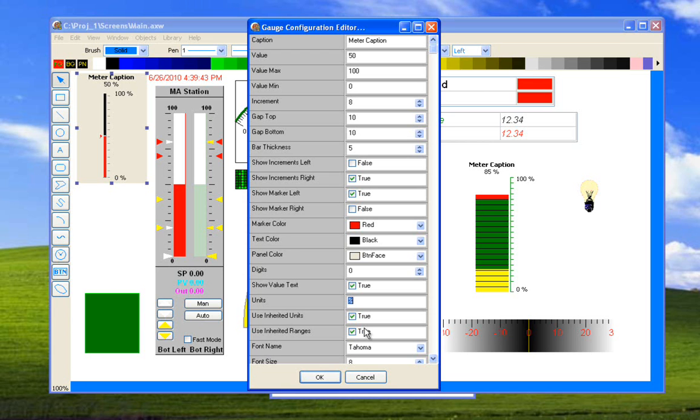And this is provided for a way to change the analog point range without having to go and locate any gauges that reference that analog tag and make changes to it.